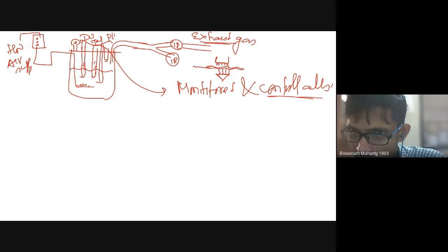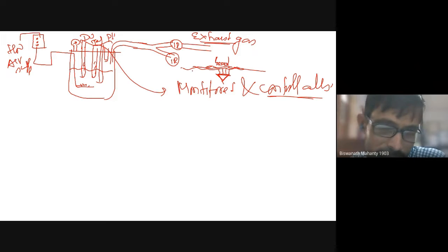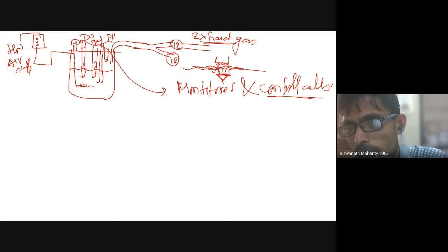So what is the principle? We have an infrared light source, and here we have the infrared receiver, and in between them the carbon dioxide or oxygen, whatever gas, is passing. Depending on the concentration of carbon dioxide, the deflection of the IR can happen. What it is measuring is how much light is falling on the receiving plate.